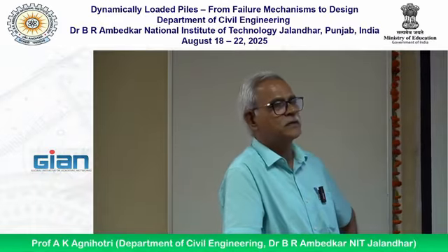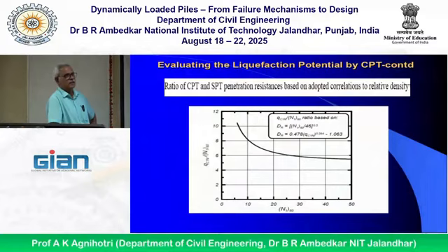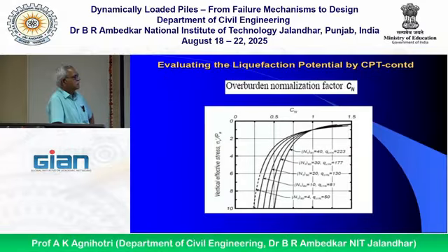There are some correlations also between static cone penetration and N160, QC1 and N160. If you perform one test, in the other value you can get some correlations. Some people have given some correlations like this, between N160 and QC1 values.